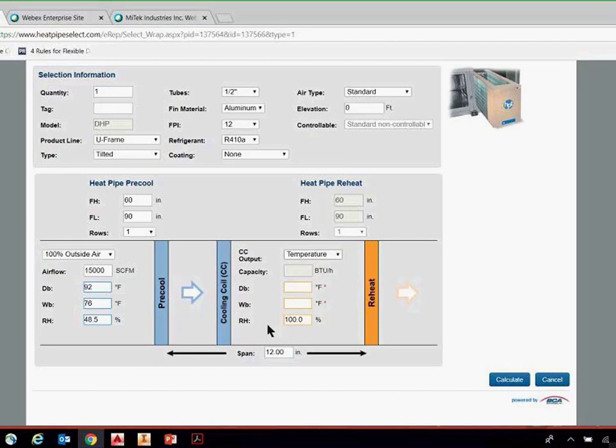All right, so next is your cooling coil leaving air temperatures or conditions. And we have two options. We can either input temperatures, dew points that you're looking for, and we actually do fixed capacity. So fixed capacity is really going to apply, I think for the most part, with DX systems. And I'm going to start with the fixed capacity, and then the next example we'll do temperature inputs, because the fixed capacity, when you get into the situation where, again, you have a DX system, and you have a certain tonnage, you don't want to go more than that tonnage because of cost.